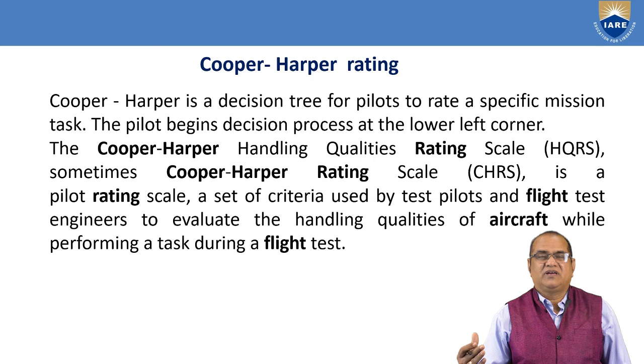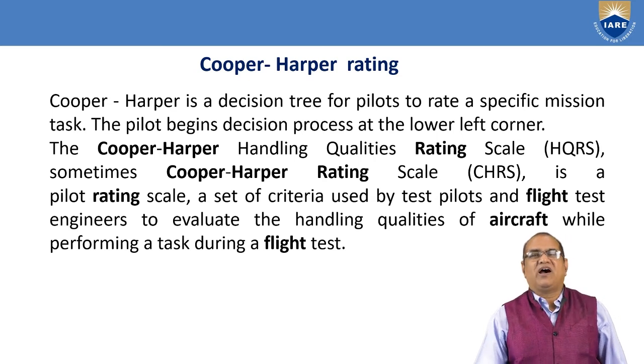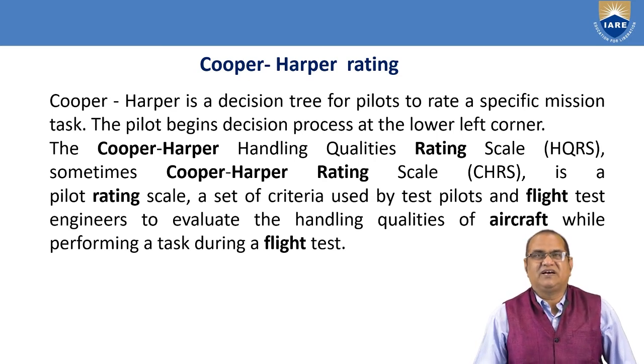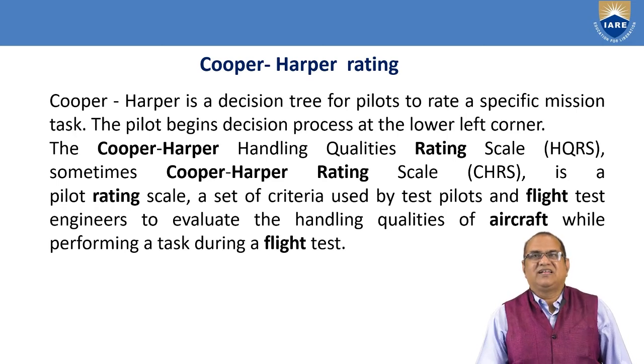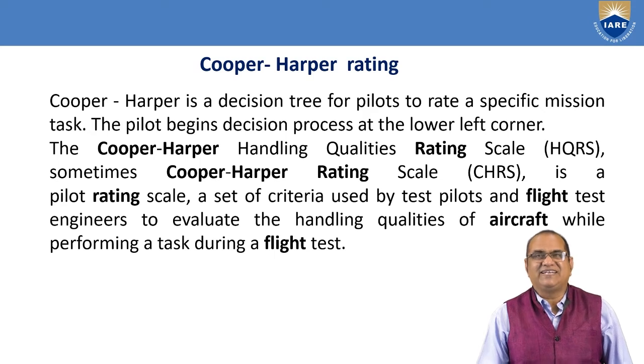The responsibility of this Cooper-Harper rating stands with the pilot of the aircraft as well as the flight engineer, and these people will decide this rating, and it indicates the quality of the aircraft during flying. How smooth, how difficult, how sluggish the control is, and all the parameters are understood by understanding the Cooper-Harper rating.